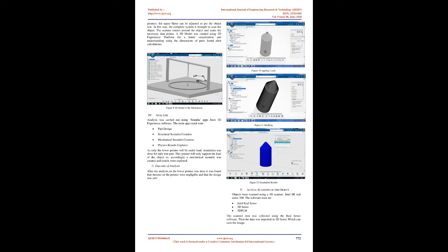Power transmitted by belt for design purpose, kW max, equals 1.5707 kW. The power transmitting capacities of belt are developed for 180 degrees of arc of contact. The actual arc of contact will be different in different applications. Angle of wrap for driving wheel equals 230 degrees. Therefore, FD equals 0.86, from design data book.